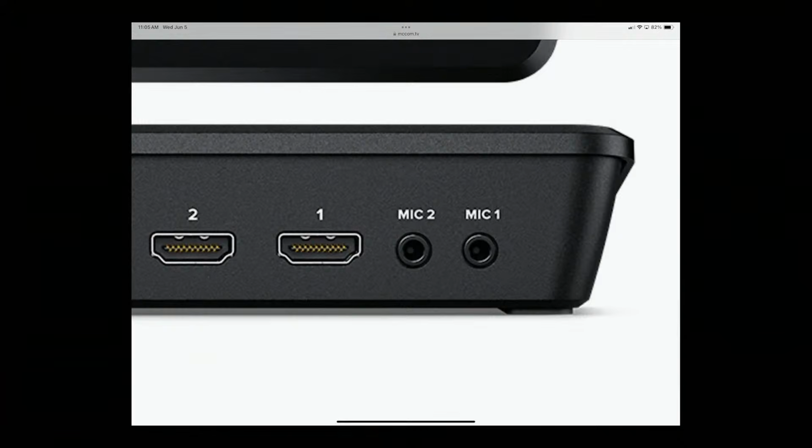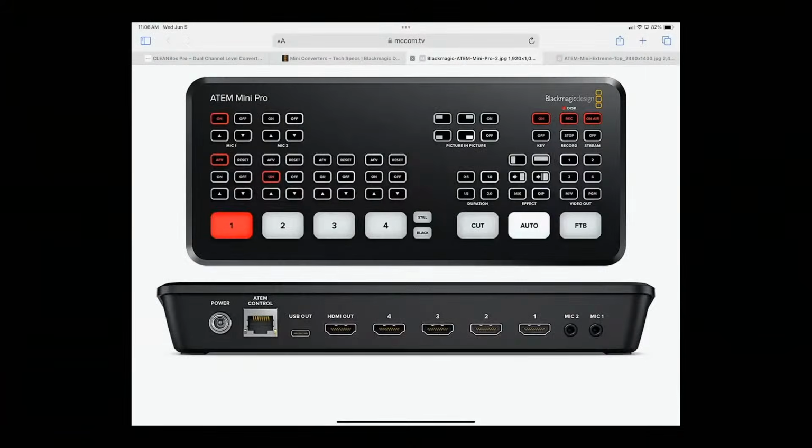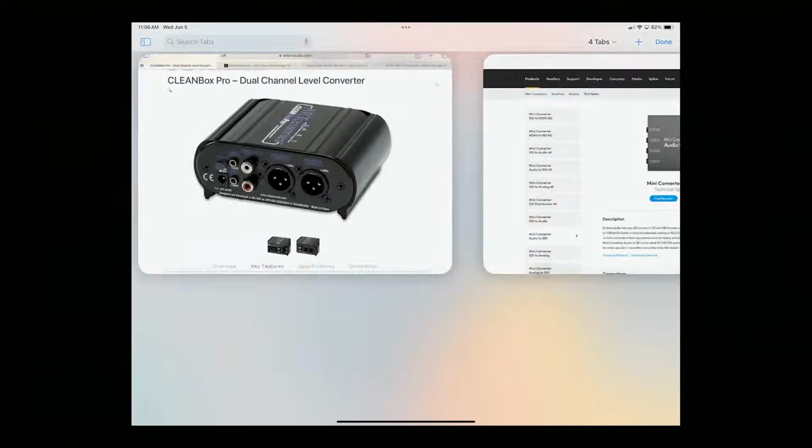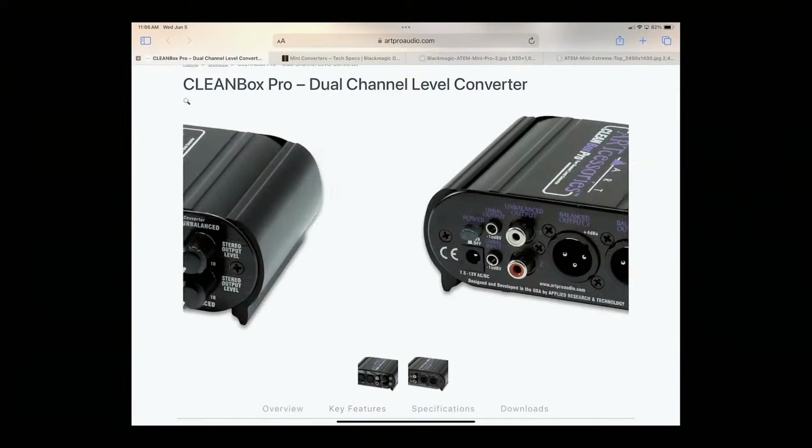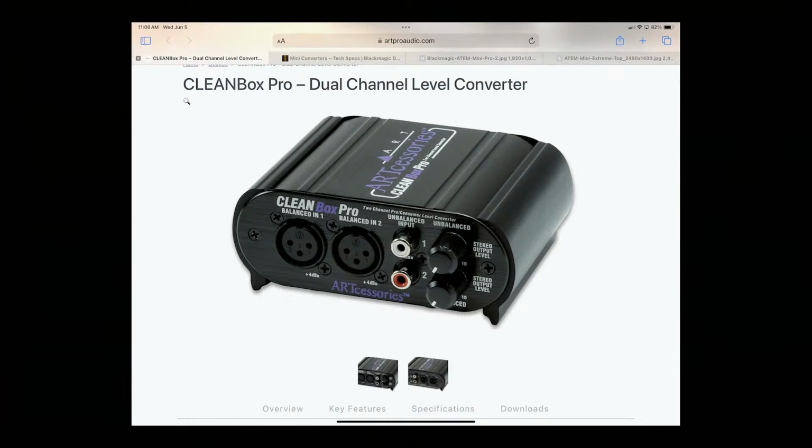And it can either be mic level, or it can be line level, or it can be mic level with camera power, 5-volt mic power. So that is an option for bringing actual pro line level audio in here, but we're going to need to do something that will translate that audio from pro line level balanced +4, usually on an XLR, into 1/8 inch consumer level unbalanced.